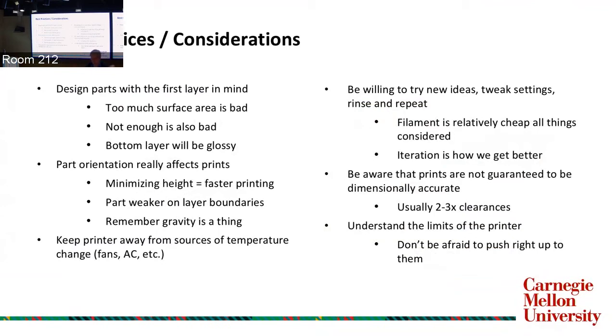You're done. Just try again. It happens all the time. Parts peel up in the corners and things like that. So you want to try to have just the right amount of surface area with the bed. Too much, bad. Too little, also bad, because your part may get knocked over or just fall over. It happens.